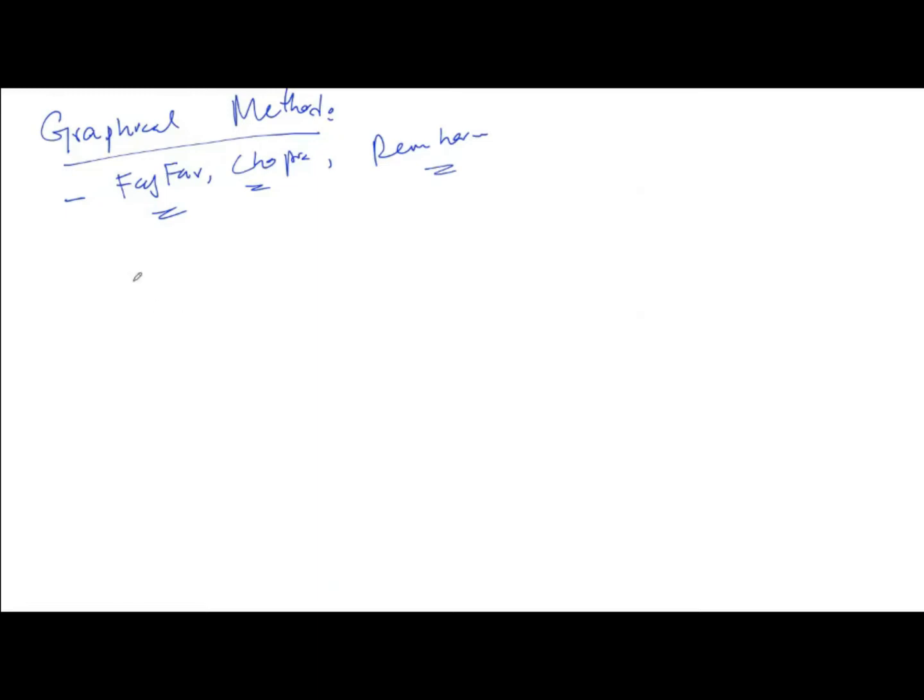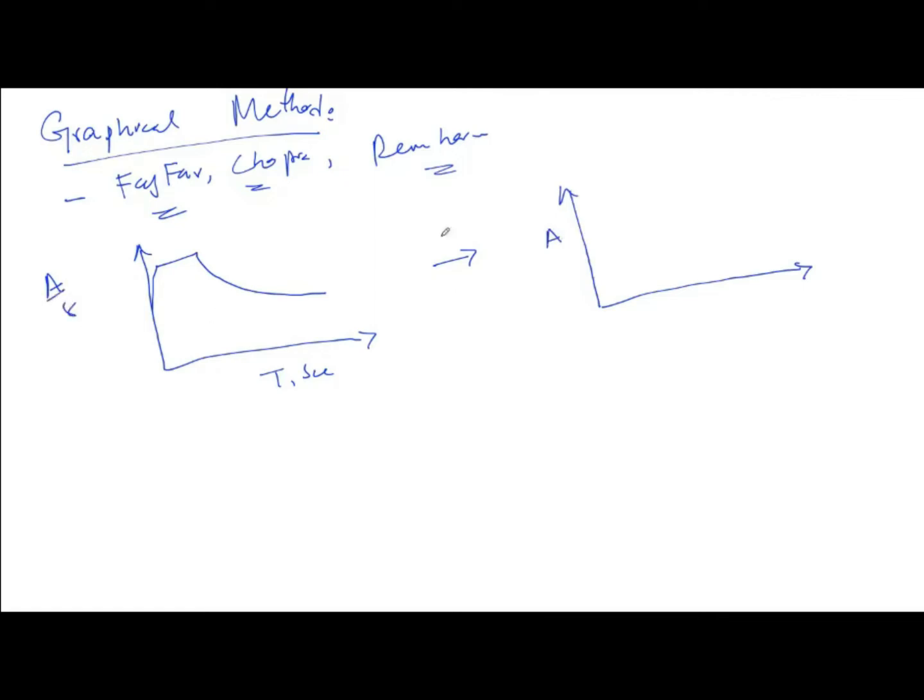So what is happening here, let me just write here. In this procedure, we know that the classical acceleration spectrum, which looks like this, with the vibration period in seconds, is converted to another spectrum where acceleration is on the y-axis. This is acceleration divided by g, and there is a displacement D on the x-axis.